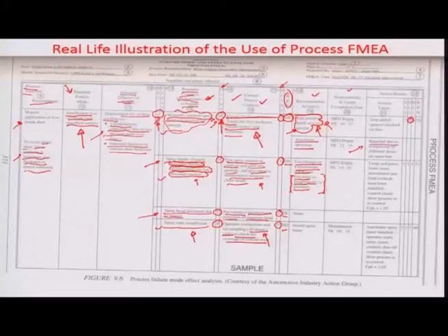And so this DOE gives you an idea of what is going to be the optimum parametrics in terms of operational viscosity, temperature and pressure values. Also, an additional checkpoint is recommended by the QA, where a fraction defective chart is plotted in order to show how many problems of insufficient wax coverage result.